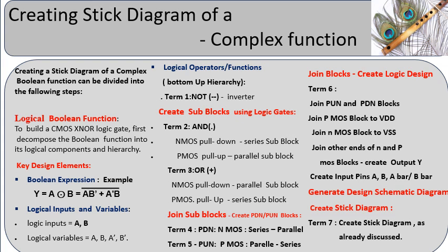Following are the steps involved in creating a stick diagram of a complex Boolean function. Minimize and optimize the Boolean expression. Identify the logical inputs, A, B, A bar and B bar. Identify logical operators, NOT, and AND/OR. Create sub-blocks like inverters, series chain sub-blocks, parallel chain sub-blocks.